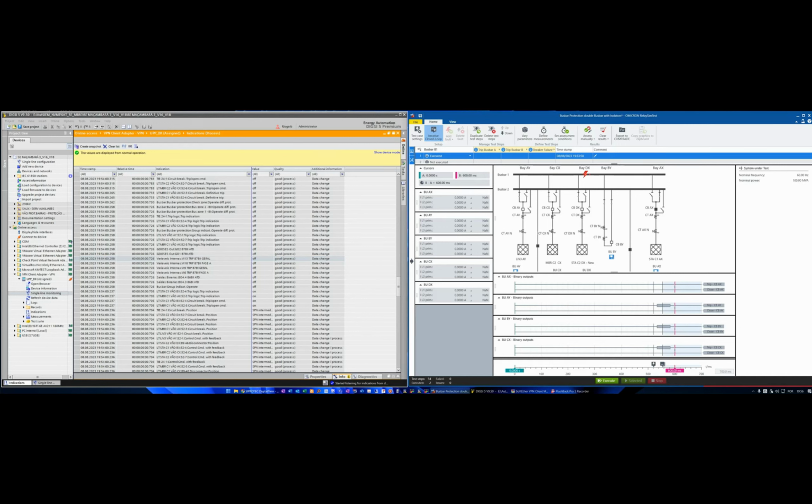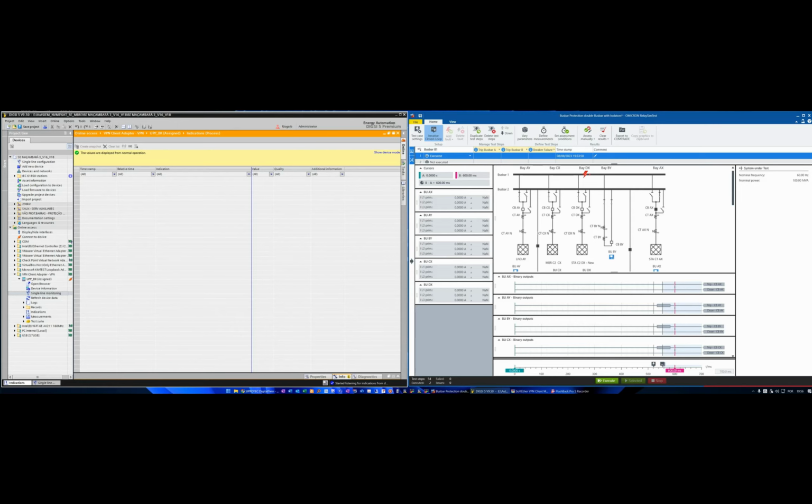So now what I want to show you is, if I change a bay connection to another bus bar protection, I can test this one. So let's do this. I will clear this event, and now we change this bay and put this bay, I have to clear the results. Now I will change this bay and put this bay in bus bar protection 2, and I just give a fault in bus bar 1. So let's do the play.